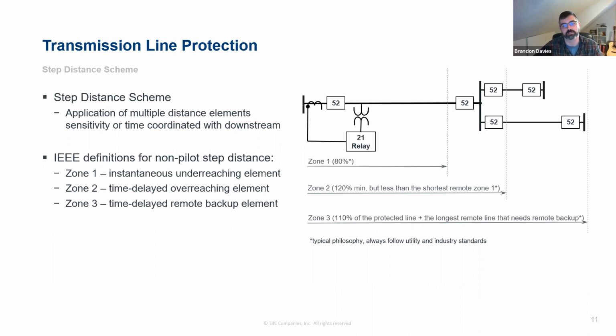So the impedance for that phase, or the phase to phase, and the way I'm going to go over distance protection is oversimplified to how it actually works. It's fairly complex how it goes on in the relay, because you're looking at different distinct elements within a phase distance that specifically target phase to phase, between A and B, or B and C, or C and A, and other things like that. So just looking at this broad level is fairly oversimplifying it, but in general, it's good enough to do that.